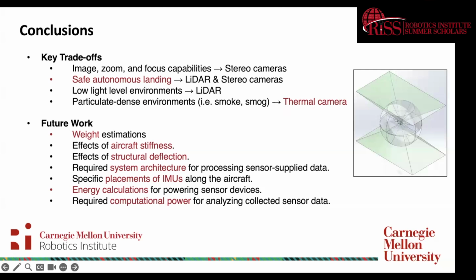Some more include required system architecture for processing sensor supply data, specific placements of IMU devices along the aircraft, energy calculations for powering sensor devices, and determining the required computational power needed for analyzing collected sensor data.